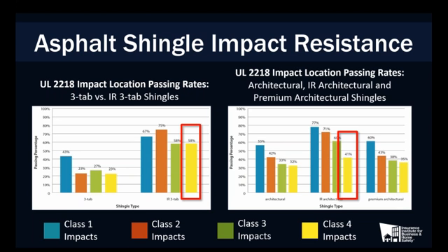And we know that as products sit, they actually become more brittle. So the longer it's sitting before we get our hands on it, the more brittle it becomes, which makes it more prone to cracking. After we talked with them, they recognized through our research and through their own market surveillance research of off-the-shelf products that the testing frequency wasn't really capturing the true off-the-shelf product performance. So Underwriters Laboratory has actually increased the frequency of their physical testing.